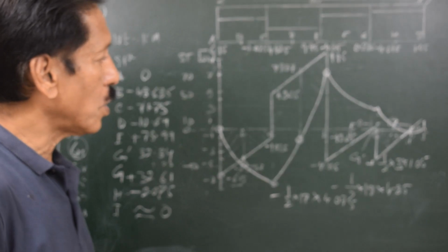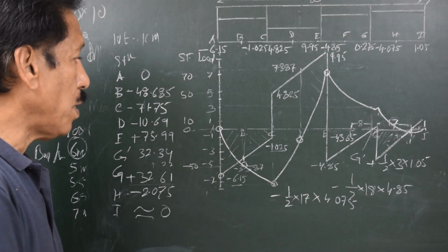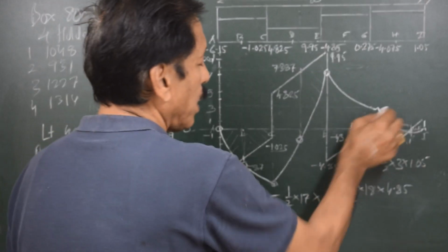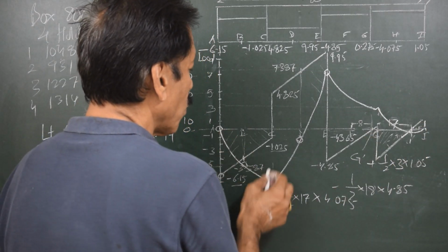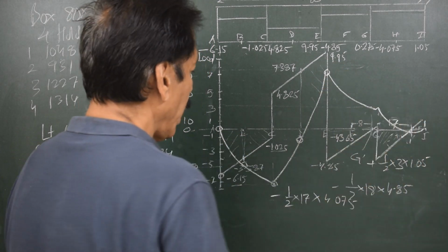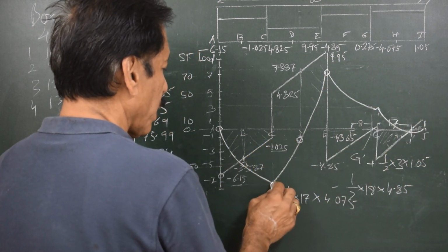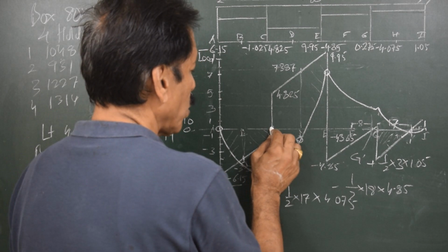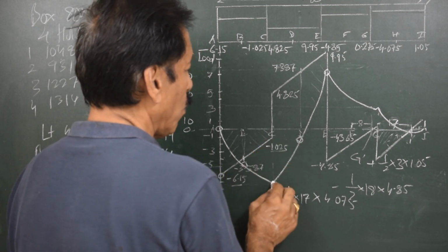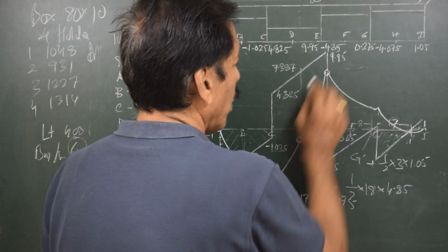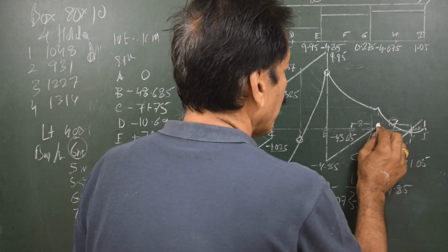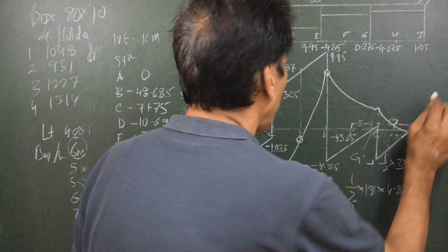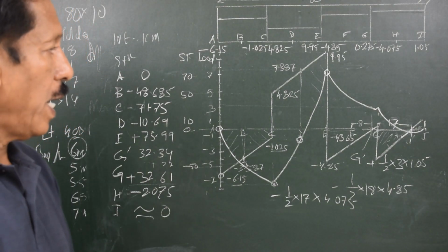So this is how the shear force curve can be drawn. So when the examiner checks your curve, he sees that the previous curve is going upwards, right? And throughout you have drawn the shear force curve with the center of curvature upwards. Very nice. He sees that the previous curve is having a peak value over here. The previous curve is changing direction from positive to negative or negative to positive. We have a peak value for the next curve, maximum peak value. And you can see here itself, here also you have the peak value, then you have a peak value over here also, and finally the shear force that starts from 0 ends at 0.